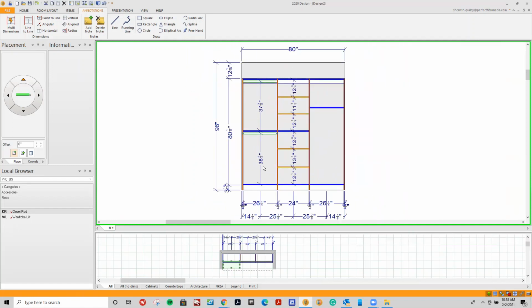And now I have 37 3/8 for the top and 38 5/8 as my variance. Majority of the actual hangs are going to be roughly between 36 and 42 inches, depending on how tall people are. Always indicate from the actual client what dimensions they need. Some might be 6'5" or 6'7". You have very tall people, and they're going to need a taller module and more space. But the majority and the average user is going to be between 36 and 42, 41 inches.